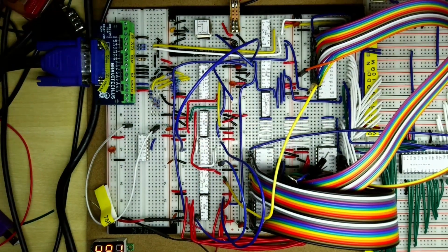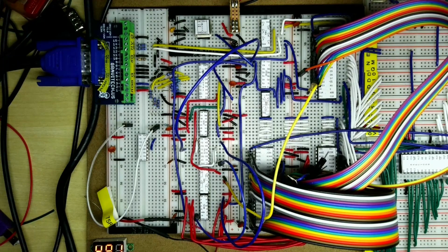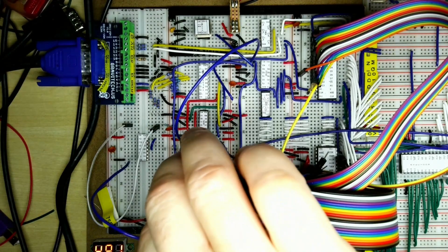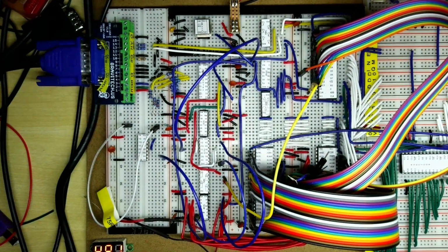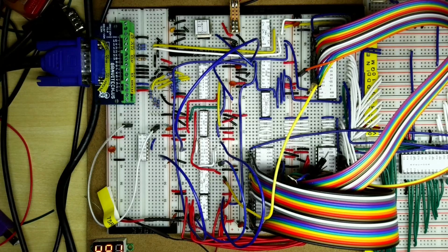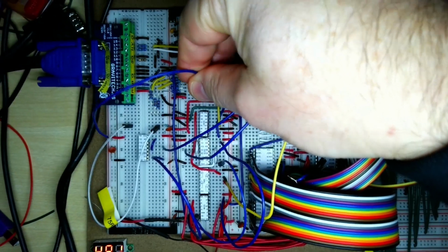So I've unplugged that, and then what we're going to do is to use this flip-flop down here. So first of all, we need to provide a clock for the flip-flop. So that's going to be using the same dot clock that we've got down here on the shift register. The dot clock goes in there. Now we need to take the output from the display enable inverted signal over here, and we're going to treat that as our input. So this needs to go into the 4D. And then finally, we've got the display enable signal going into the buffer chip here.